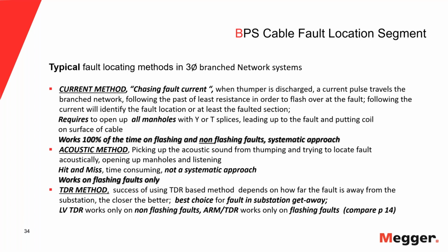Aside from the fact that it's sometimes very hard to locate the acoustic signal. People go down in the manhole, they listen in the conduit, they try to really do all kinds of things. It's a hit and miss approach. I have to say that, and it's not a systematic approach. Okay, and it works only on flashing faults.